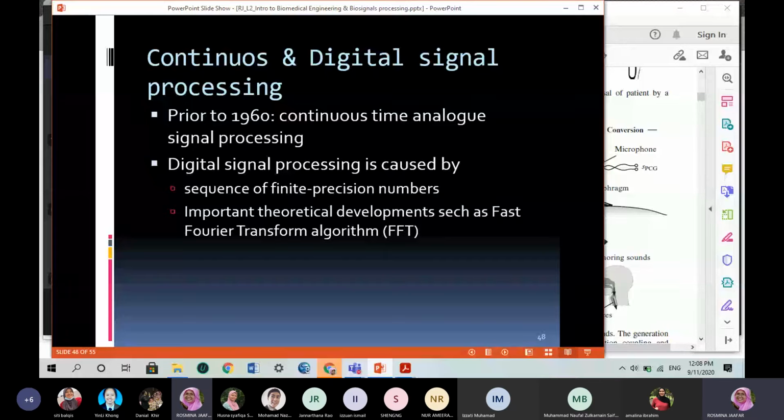For example, with analog signals, it will take a long time, and it will be based on an individual person's effort, and then you will have high inter-observer variability for analog signal processing. For digital signal processing, we have removed the inter-observer variability, because the computation is just one program. So there is no chance of inter-observer variability, because it is the same computer, the same look.